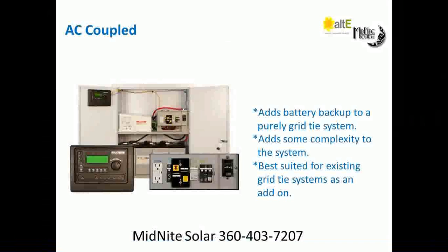Those are the hard questions you need to ask yourself when you're looking at doing renewable energy: do I really want to go purely grid tie, or do I want to add some batteries to this? And that's a hard decision to make at the time of writing the check, because the batteries do add a cost to the system, and a lot of people will go with the less expensive route for quicker payback, and then unfortunately something like Sandy comes through and you realize that your $20,000 system still let all your food spoil in your freezer and your refrigerator. So definitely take a hard look at that, think about it, and really weigh your options as far as battery based versus purely grid tied.